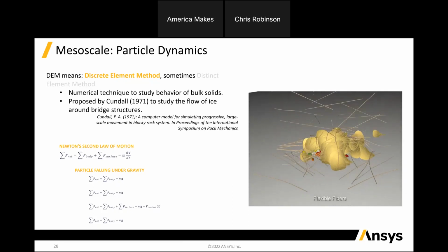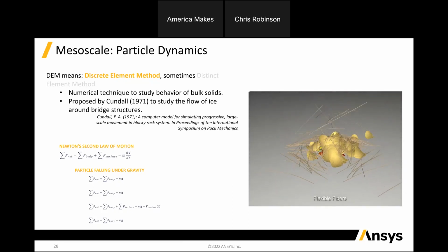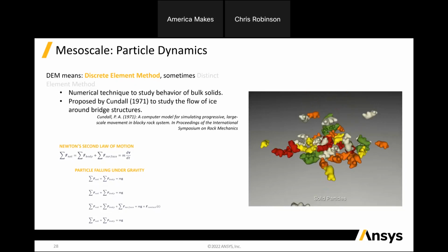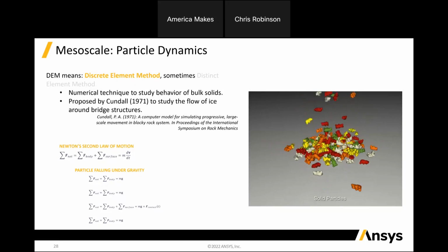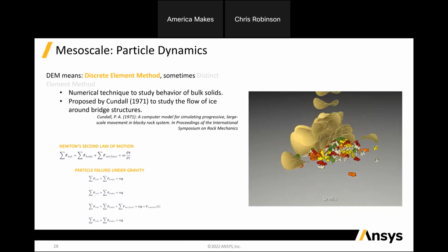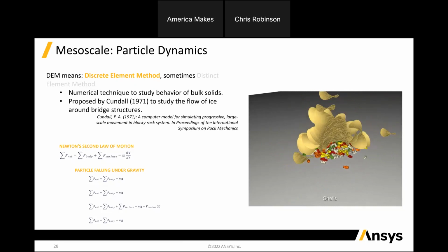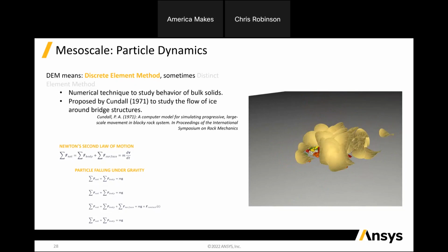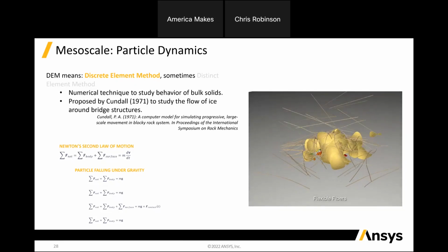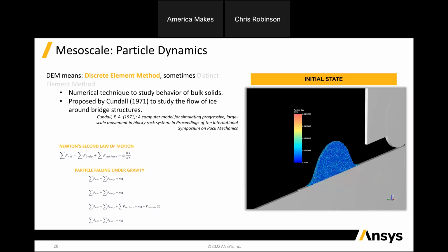and you're modeling them. So when it comes to particularly laser powder bed fusion, again looking at the metal process here, we've got some different laws that we can put into play. Newton's laws are always there, gravity is always there, and you can start to apply some of those laws to individual powder particles. So this is something that is available within Ansys to be able to go through and do discrete element modeling.